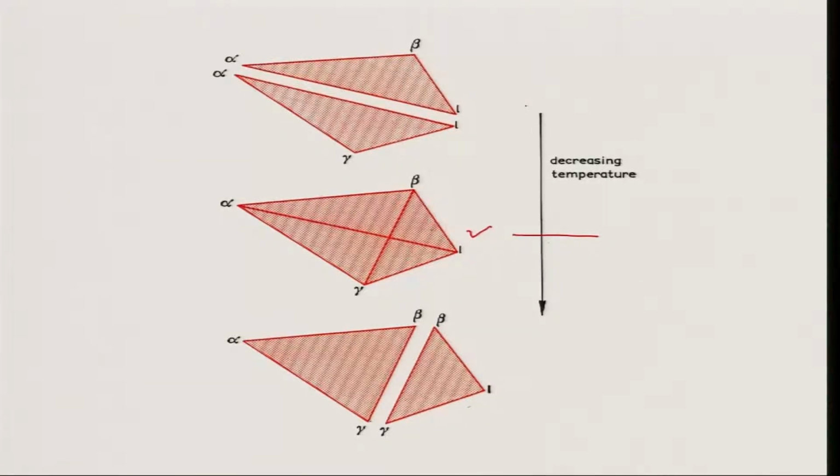What I am saying is that these two can be either peritectic plus eutectic, or both eutectic. If it is peritectic plus eutectic, that means liquid plus alpha will react and form the beta phase for the first 3-phase equilibria. The second one, liquid will transform directly to gamma plus alpha, correct. Otherwise, both of them can be eutectic also.